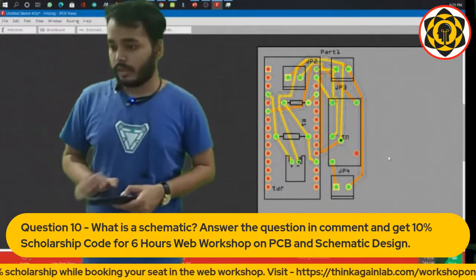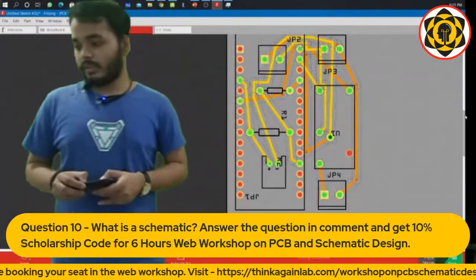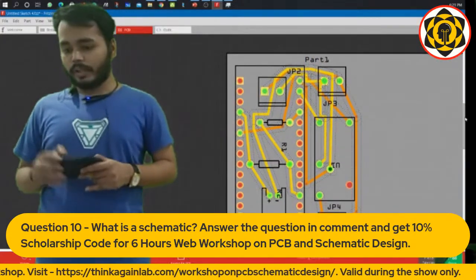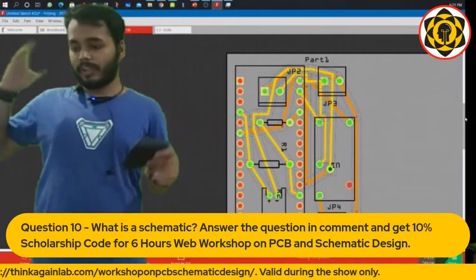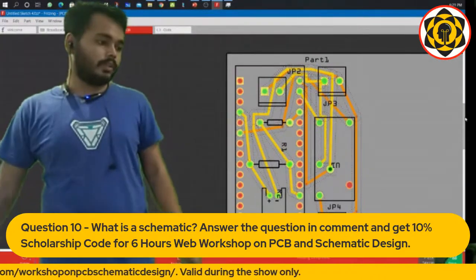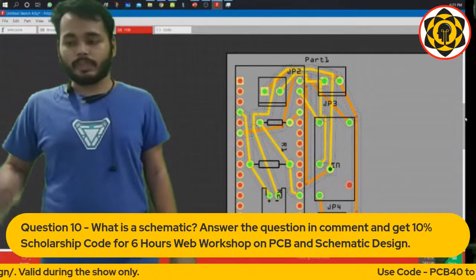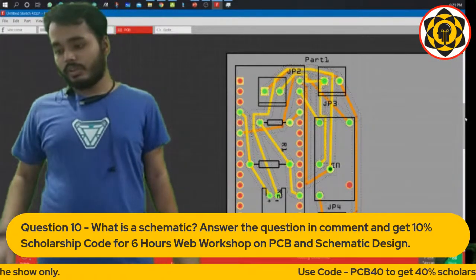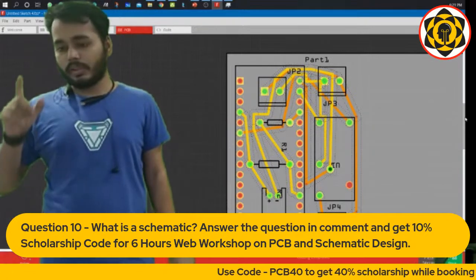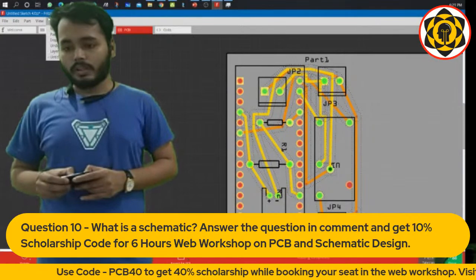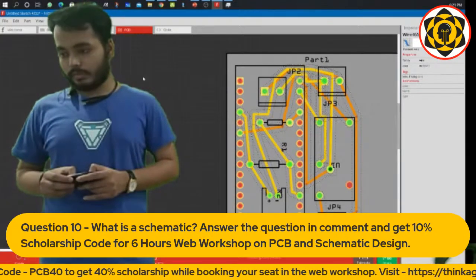Now comes the question of traces. Whatever wire we are using for the 5-volt side, can we use the same wire for the 220-volt side? Because that's a lot of voltage, and a lot of current, depending on whatever bulb you are connecting to this. So here I will suggest that you increase the trace. How are we going to do that? We are going to go to the inspector.